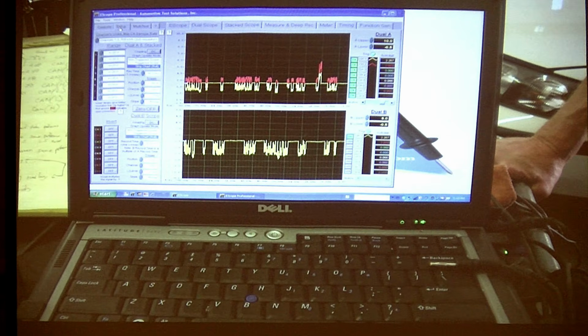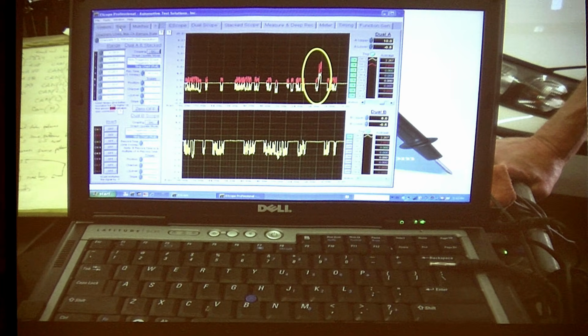Here's my system. Do you see that guy right there? That guy is who I'm interested in. That's a module that's failing. And that module has a problem to where the CAN transceiver is failing. And that CAN transceiver, when it's failing, it's putting noise on that bus, and I'm failing all those other modules. Does everyone understand how this is working now? We understand how the system is in operation and how we count to get codes. That guy right there, that's the module I'm interested in.